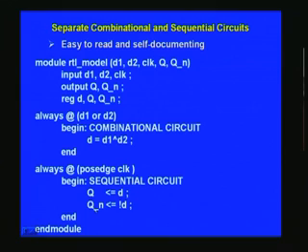And this we have also seen earlier, and this is nothing but an inversion of D. If you look at the synthesis tool later on, you will be surprised. D need not be put on the port list at the top, because this is not an input as such. It is only an intermediate output, and I will come to that in a minute. So here we are inverting this D